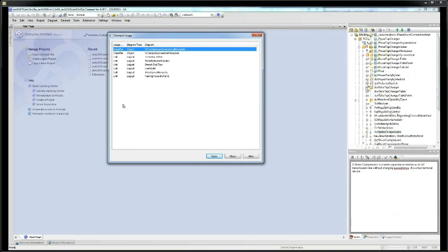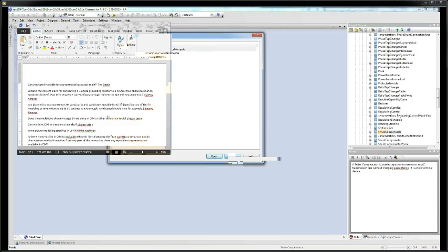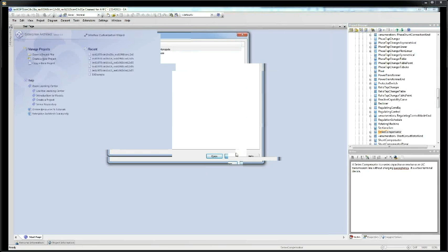So it looks like a series device, like an AC line segment or a transformer. You basically would have your power transformer connected with phases A, B, and C at the terminals, and on one side, to the other side of the connectivity node, you would have a series compensator with the necessary attributes filled in, with the series reactance and whatnot. This would be the class you'd use. And you see these out on lines, you see them in substations, however they need to be. So you can define both the series reactor or a series capacitor. Hoping that properly describes what you're looking for.